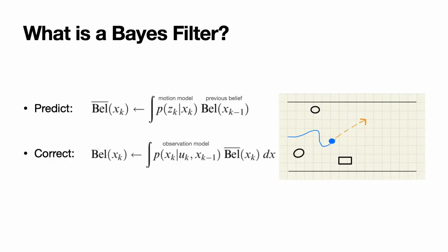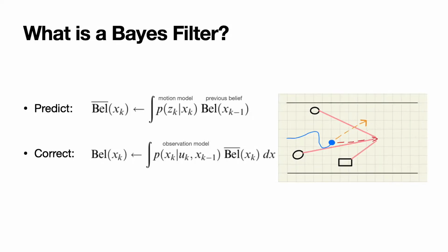Let's look at an example of self-localization in a previously drawn map. Obstacles and walls are indicated by black lines. Our previous rover position is indicated by the blue dot, and the yellow arrow points towards the predicted position after taking the motion model into consideration. The red arrow, however, points to another position based on the observation model. A laser scanner on the rover might have measured that the obstacles in the map appear to be at a different distance than they would be if we were to believe the motion model.